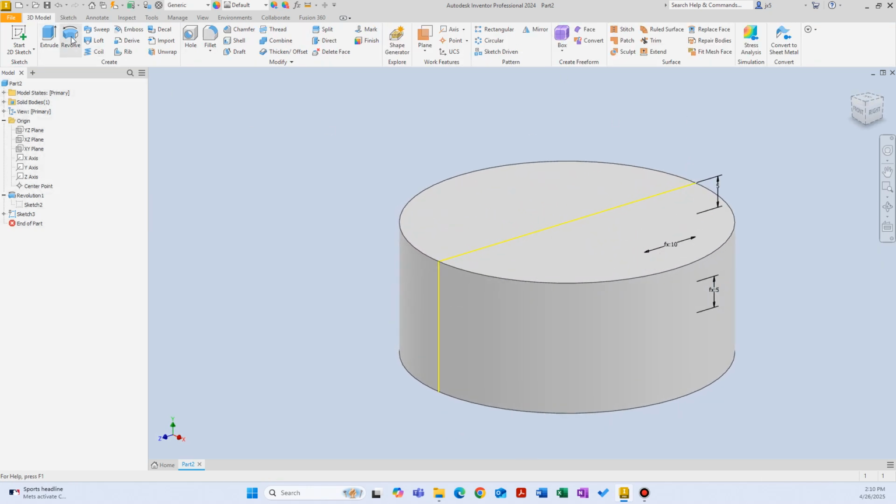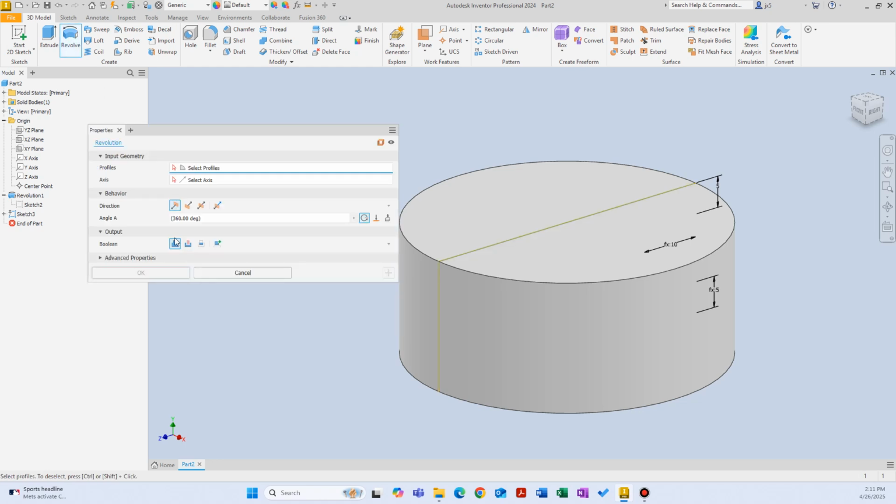And now let's click on Revolve one more time. Notice that I have more selections this time. And also it did not select it automatically for me because there are multiple options. I can select this or I can select this here. So let's select this inside the rectangle we drew here. And now it is asking for axes. Sometimes it is not automatically activated, so you can go ahead and activate it. This blue underlying color appears here, telling you that it is active right now,